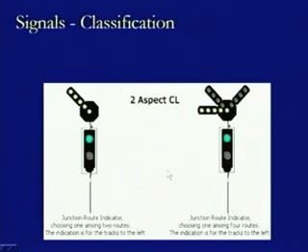This is one route signal which is being shown here. This may be of different types. If there are only two routes, one main route and one other route, then this is how it is defined. We have a color aspect signal shown here with another color aspect signal and a movable arm. If it is provided in this form, then the track to be taken is on the left hand side, and this particular track is to be taken by the train, and the green light indicates that you are allowed to move further and take that track.